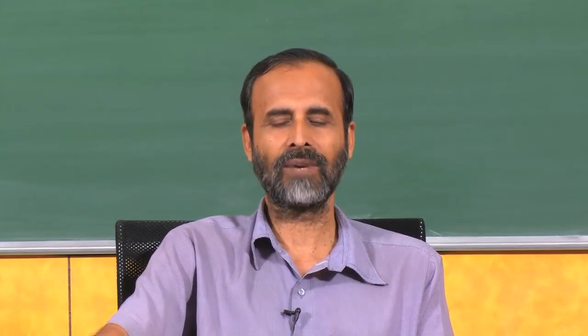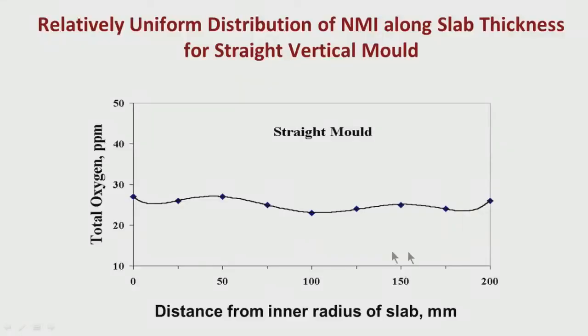So, whatever defects were inside the cast slab, as you are rolling it, this 200 millimeter thickness will become, when you are hot rolling it, maybe 5 millimeter or 6 millimeter or maybe 4 millimeter. So, whatever defects are distributed in the whole bulk of the cast slab will try to come to the surface because the surface area is increasing. So, the more you roll, the more defects get exposed to the surface.